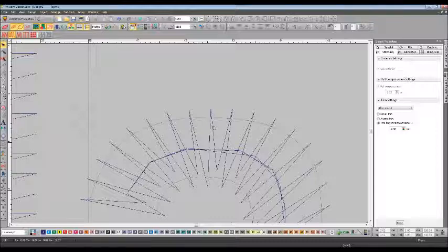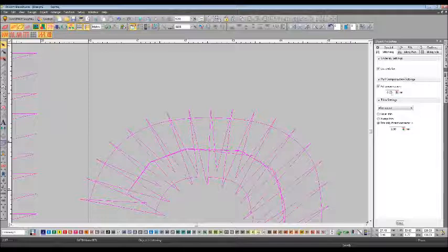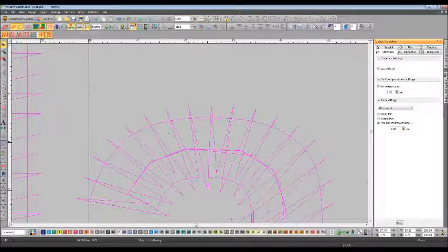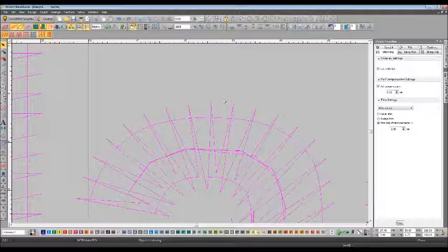And what setting do you need? Well, the computer sets that for you automatically depending on the fabric that you have chosen in your project. But because you have the ability to adjust that here, you might want to add a little more. So if we select this, if the PK is a thicker PK, we can add a little bit more, change that from 0.2 to 0.3 millimeters, and you see the difference.